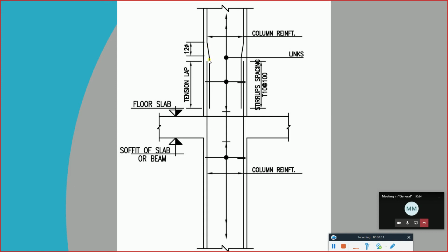So here, if you can see, we bend the steel. That's why yesterday I was saying that if you have more than 25 diameter, it's going to be very hard for you to bend. So this is one case of bending due to lapping. Visual lapping, this is what you can see. The lapping is occurring here, the intersection point between the reinforcement of the bottom column and the upper column. We call it lapping. This happens if you have the same cross section for the bottom column and the upper column.